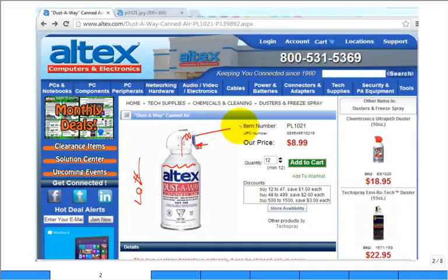But anyway, right here, if I turn it upside down, what's next to the valve when I press it? Liquid. Liquid's going to enter the expansion valve. When I do this, I can blow it on my skin. I can feel it's not cold. Do not turn it upside down and blow it anywhere near you, on your skin or anywhere else, because it will lead to a burn known as a freeze burn.